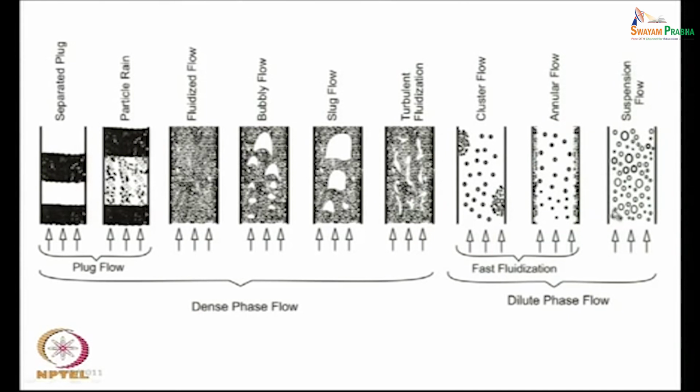We want to have suspension flow for pneumatic conveying, and for fluidized bed this particular regime occurs just as a bypass process when we want to empty the column or when the inserted sample has a wide size distribution. Only under that condition it occurs. So, depending on the application, under certain situations we might want a flow regime or we might want to avoid a flow regime, but whatever exists they are more or less similar, no matter what is the application for which we use it.